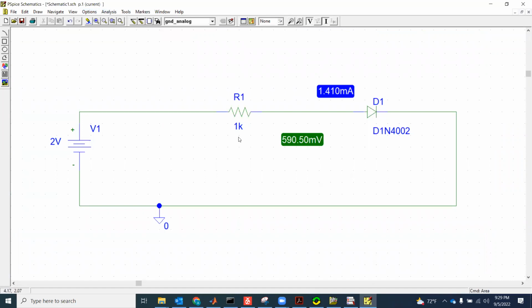Okay, what is needed in our experiment today? We need to figure out the V and I characteristics, which means I'm going to change the load current of the diode and record both diode voltage and current. How can I change that? I'm going to change that by changing the supply volt. The supply volt here can be changed to any value you need, in order to figure out the voltage and current relation for this diode.